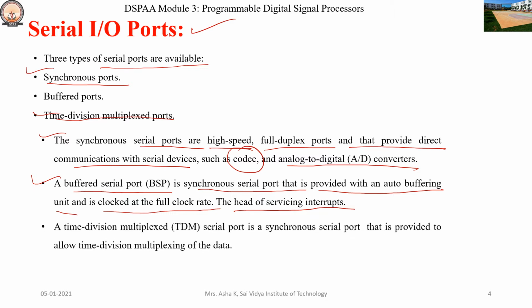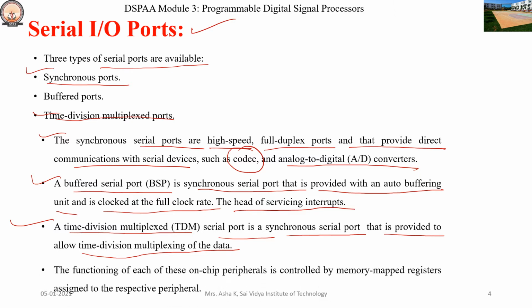We have the third one, a time division multiplexed serial port. It is a synchronous serial port that is provided to allow time division multiplexing of the data. The functioning of each of these on-chip peripherals is controlled by the memory mapped registers assigned to the respective peripherals.